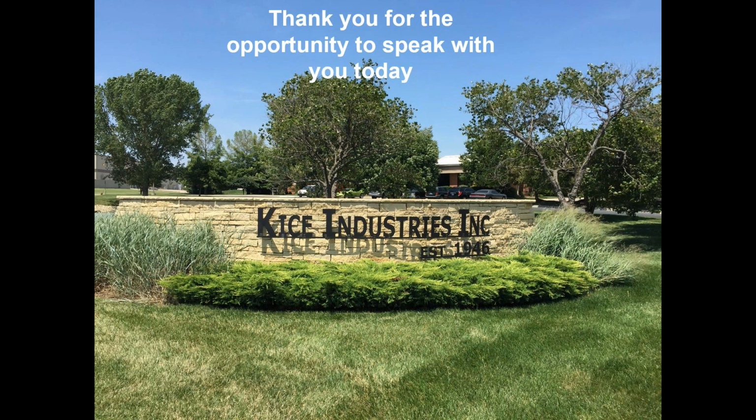It's easy to know when you're giving it too much time or giving it more time to build pressure than it needs. Each air tank on our filters is equipped with a pressure relief valve. On the high pressure cleaning systems, the pressure relief valves are set at 125 psi. On the medium pressure systems that are fed by a blower, the air tanks are set at 15 psi. So if you have a bag house and you can hear the blower ramping up, or you can hear the airline filling up the tank, and then you hear a hissing sound, you hear that pressure relief valve go off, you know you've waited too long.